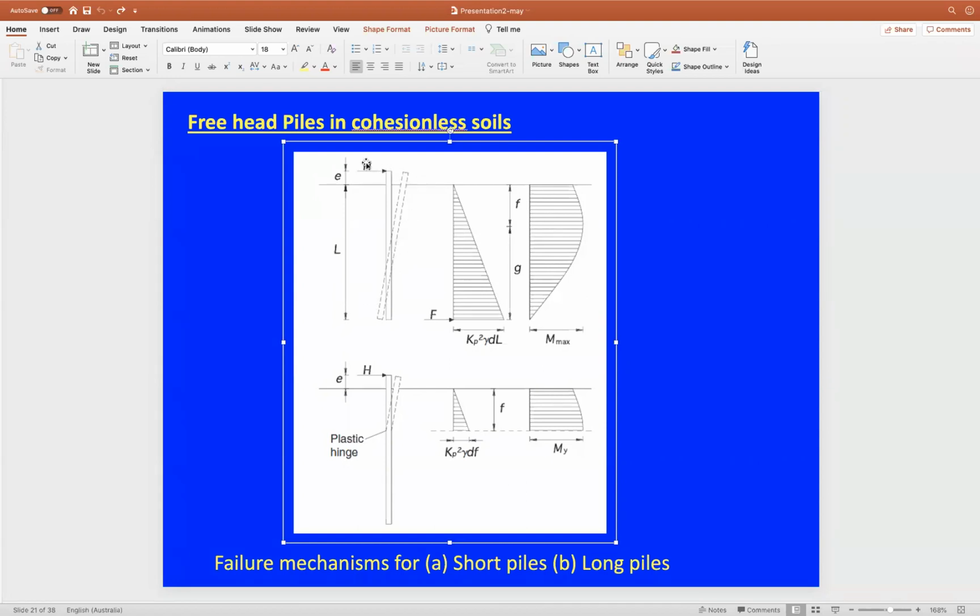So we're going to end up with the amount of H acting in that direction being equivalent to the amount of distributed forces above the maximum moment point here. So that will be equivalent to the amount of distributed forces within the length F on the system. But because here we don't have the value of F, F is unknown and H is unknown, so we cannot benefit too much from the horizontal forces. But we're going to go back to that later to find the value of F.